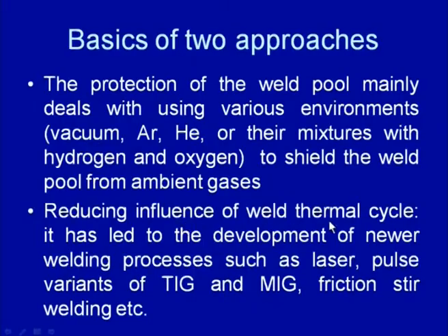And another is reducing the influence of the weld thermal cycle, which has led to the development of newer processes such as the laser pulse variant of GTAW and GMAW, and solid state processes like the friction stir welding of the aluminum alloys.